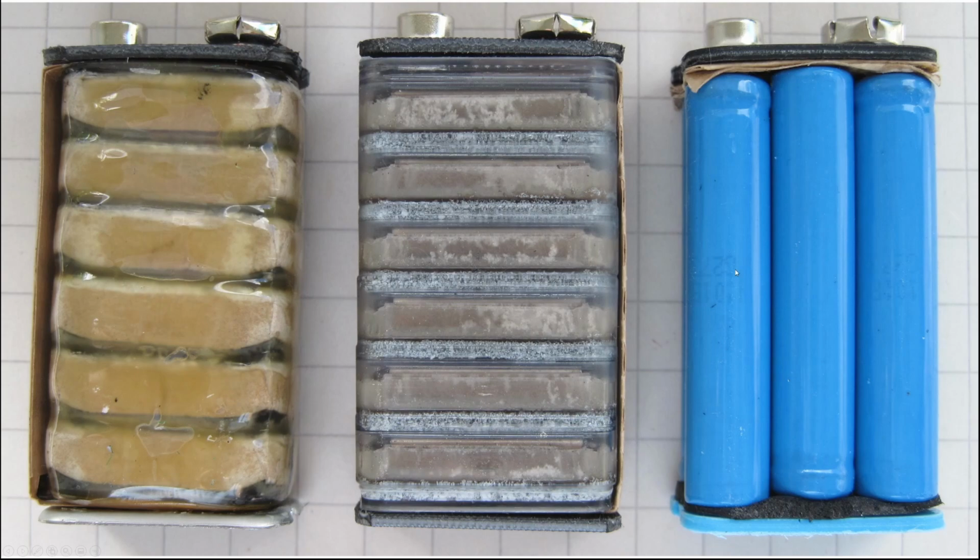These are the insides of some different 9-volt batteries. You can see a couple of different styles, but in the classic 9-volt battery we have 1, 2, 3, 4, 5, 6 individual cells inside. The type of cell we use inside a 9-volt gives about a 1.5-volt potential difference, so you get about a volt and a half from each cell. If we want 9 volts, we just string 6 of those together and we get a battery. This is what we mean when we say a battery consists of multiple cells.